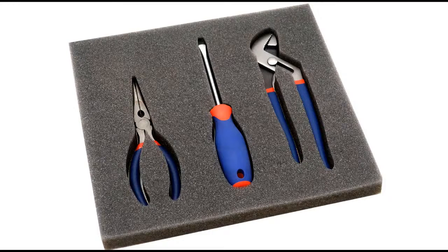If I take a photo of it, I will then have to measure the tool or the object that I'm doing and then make sure that the graphic is scaled properly. And then I can send it to my laser and cut it out for a toolbox, or I can cut it out to create a template or a graphic for that. And then, of course, I'm going to save this. If I'm making toolboxes now, once that tool's done, I don't have to do it again. Once all your tool sets are done, you can mix and match and arrange them as needed onto your page in CorelDRAW, and then cut out to your heart's desire. But it does take 2 or 3 minutes per tool or object. The more complex ones are going to take more time.